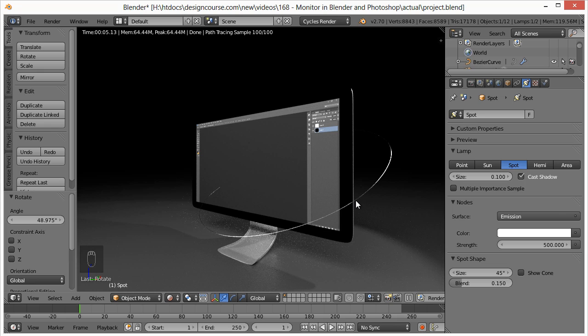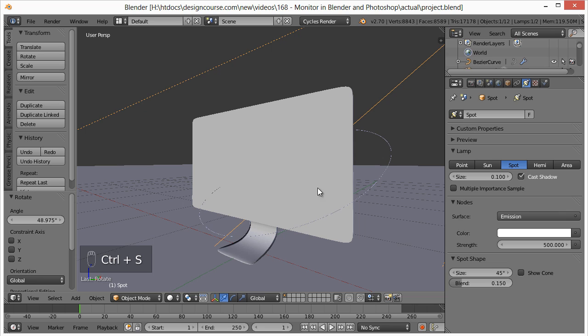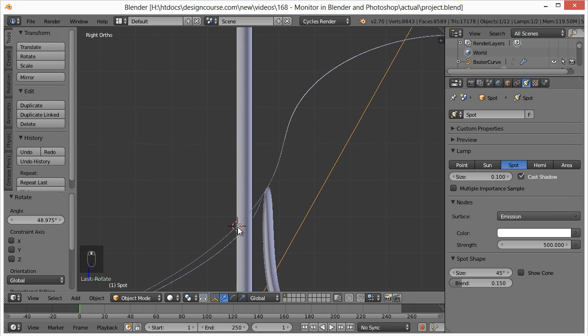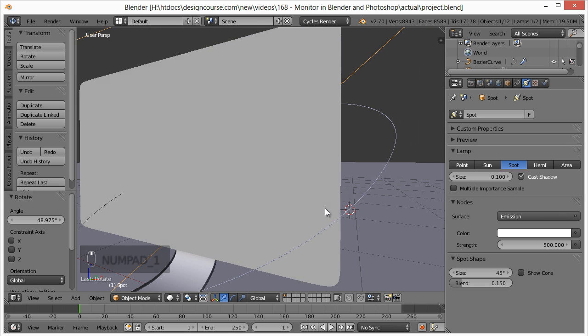All right, so now what I want to do is also add kind of like a little directional pen tool anchor points where you can see the Bezier curve directions. And so to do that, I'm going to go to solid. By the way, make sure you save your project here. And I want to add a cube right on this line. So if I hit 3, see where it's at. I hit 1. All right, it should get added right near the center of that line.